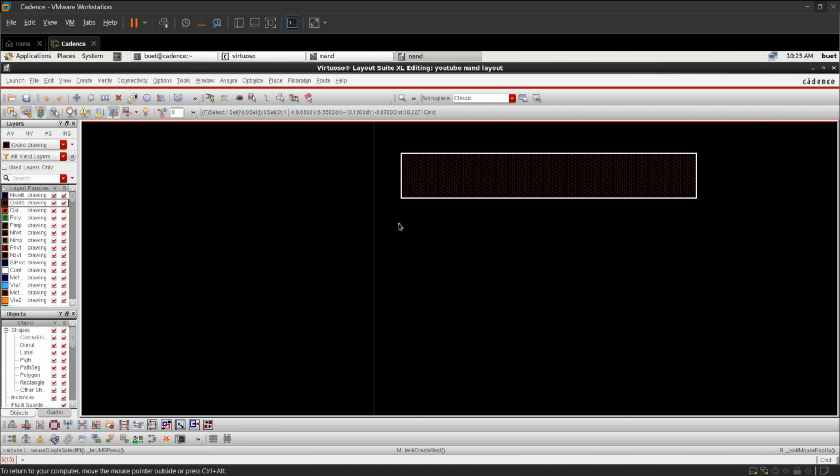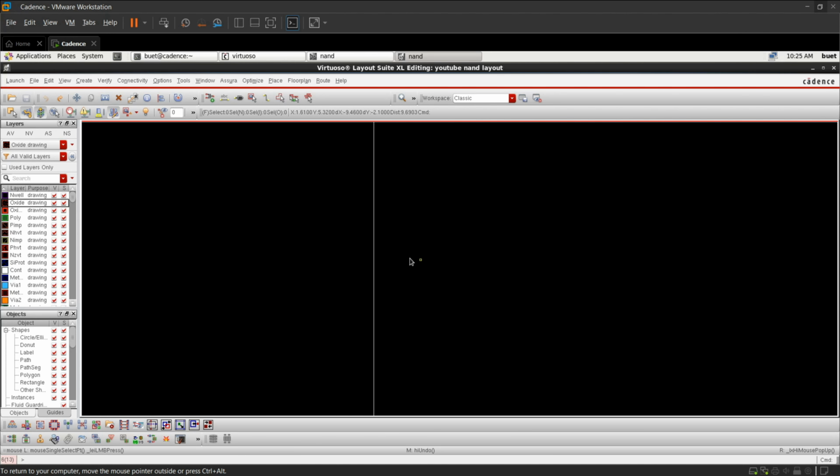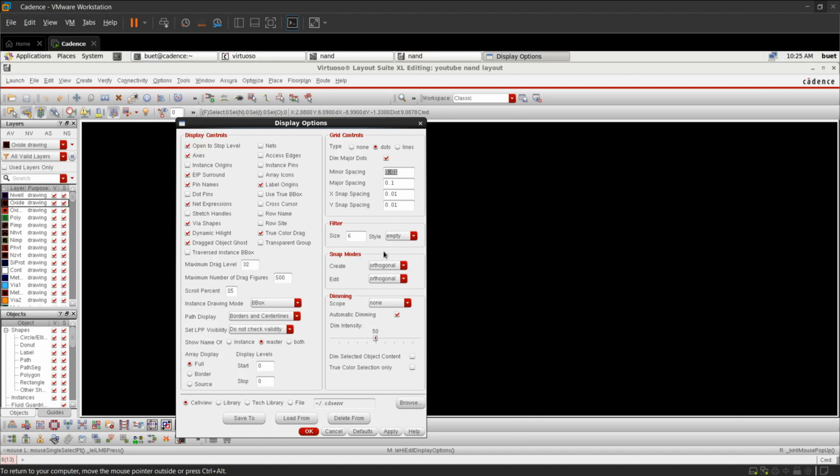Before that, we'll set some boundaries. Press C. Let it be 0.05. Along with that, even this should be 0.05. Make this 0.01. X snapping and Y snapping will be given from boundary, but right now it should be multiple of 0.005. Here we are taking directly 0.005 because precisely we will be doing this.